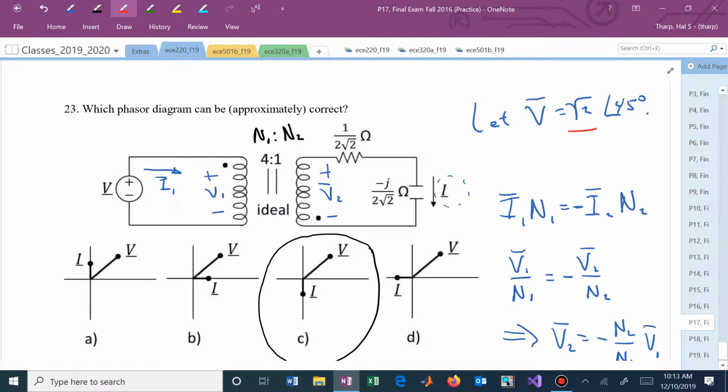We now figure out what the impedance is of this capacitor, what it is of this capacitor, and however they're interconnected, we treat them like generic resistors. If they're in parallel, we combine them as a product of 2 divided by their sum. But we keep track of all the signs in those impedances. Is that clear? That's a good question as well.